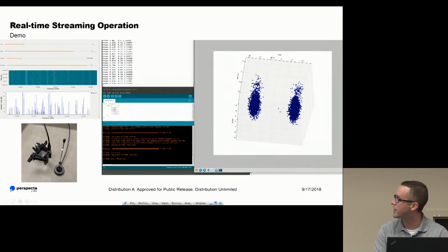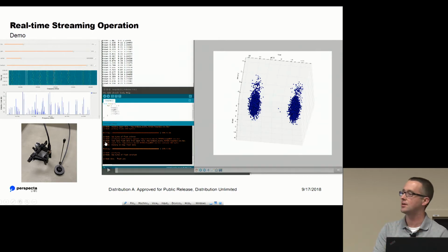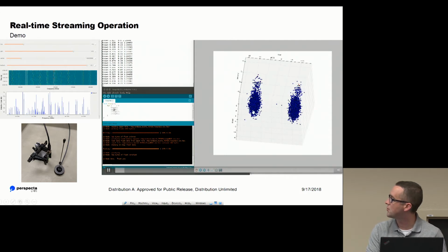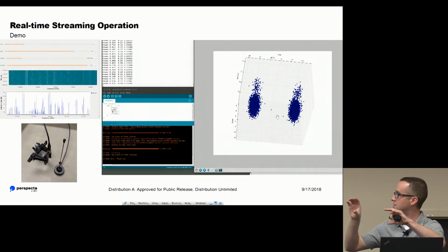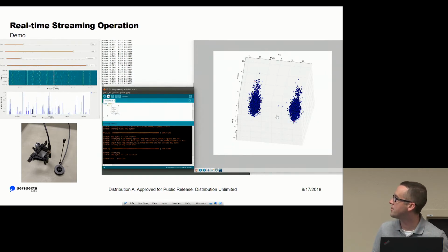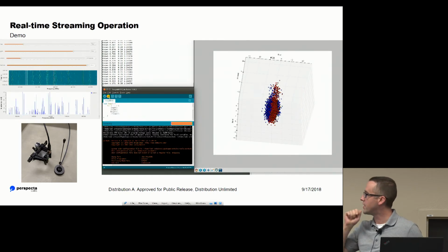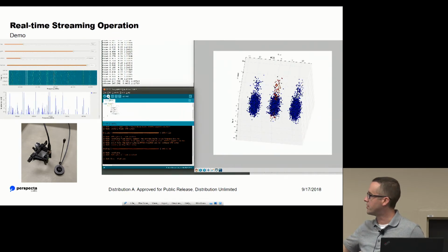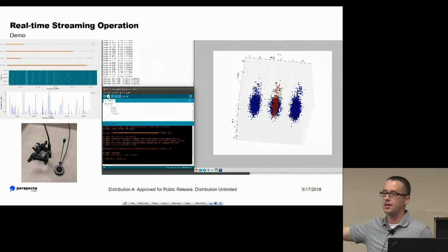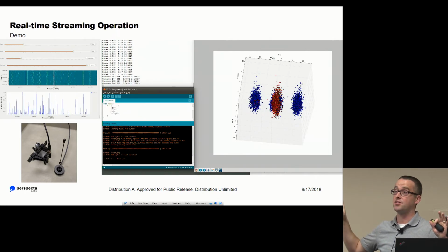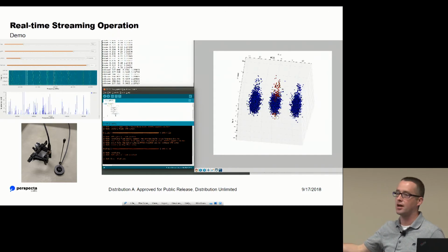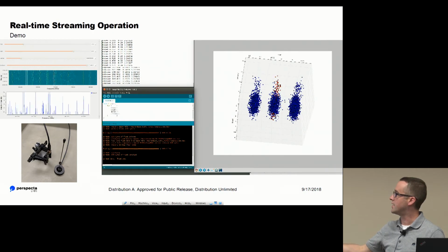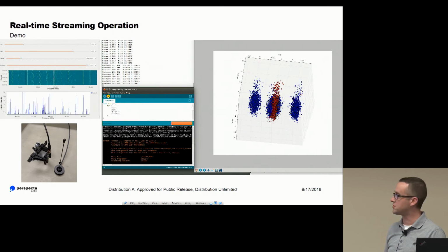So we're running our system with an antenna placed near the device. And let me play this video, see if you get a visual idea of what's going on. So in some PCA space, we can see that there's two unique things going on, state 1, state 2. Now we're going to add a third state here, load it onto the device. And so during the loader, it kind of goes wacky. But now we see a third state. The anomaly detector says, hey, I haven't seen this before. This is new. It flags that now we're seeing unknown code. And it would raise an alert to the repository.